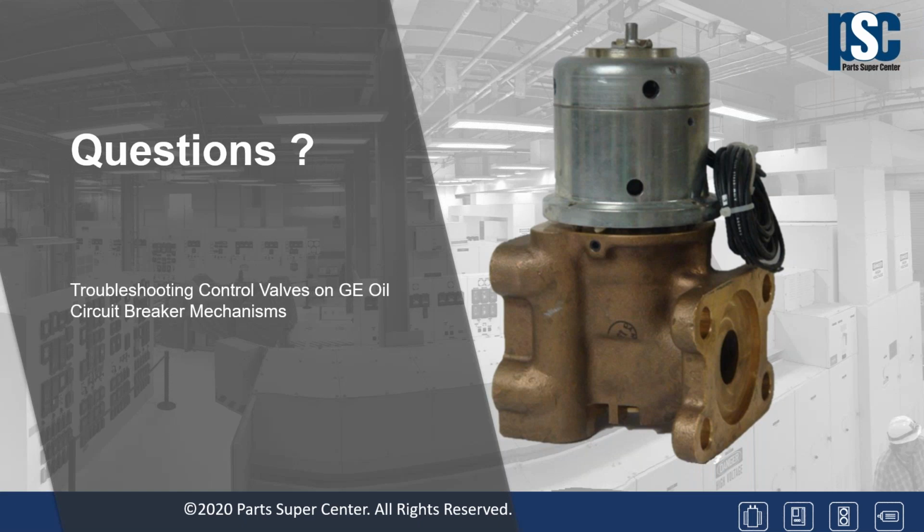However, the IEEE C37 standard for oil circuit breakers with compressed air stored energy mechanisms from the 50s indicated that you have to have 5 stored operations. So that means that the air pressure will drop to almost lockout pressure on your pressure switches, and this control valve still has to be able to operate and close the breaker successfully.